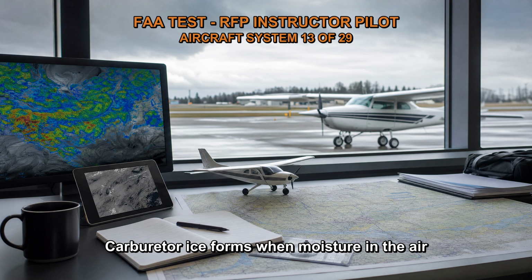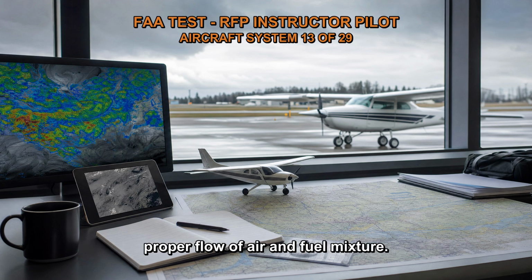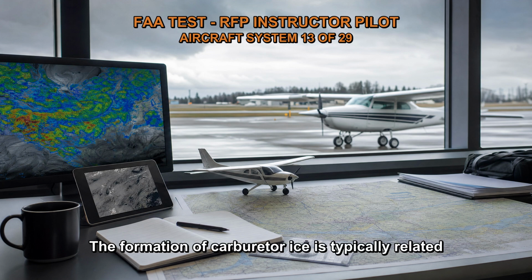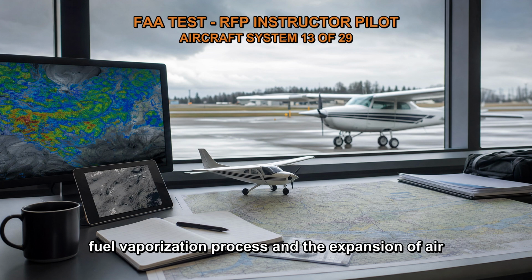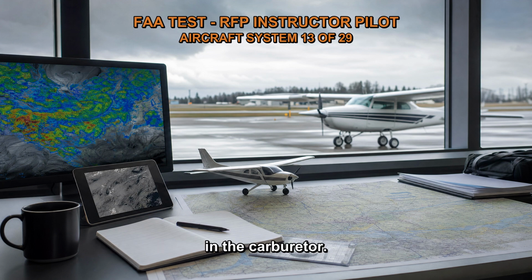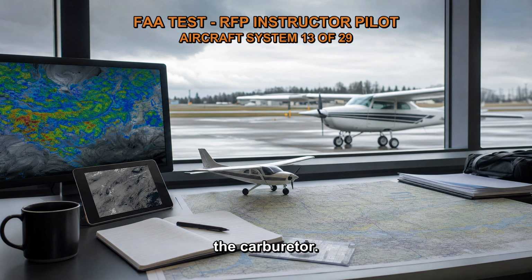Carburetor ice forms when moisture in the air condenses and freezes within the carburetor, obstructing the proper flow of air and fuel mixture. The formation of carburetor ice is typically related to the temperature changes that occur during the fuel vaporization process and the expansion of air in the carburetor. The low temperature is the result of the vaporization of fuel and expansion of air in the carburetor.